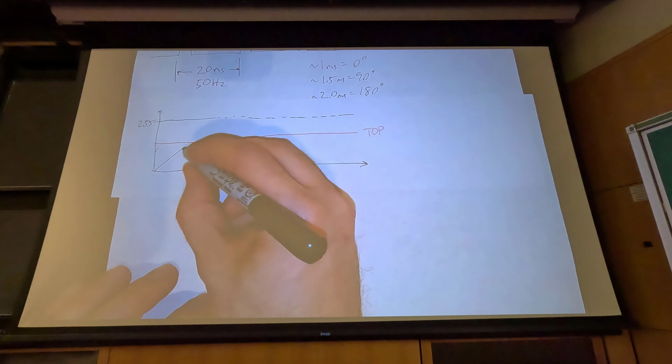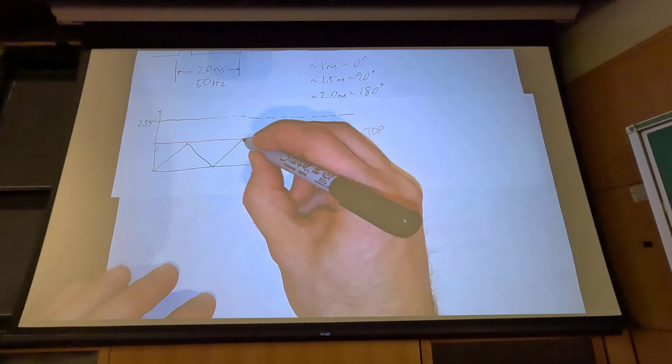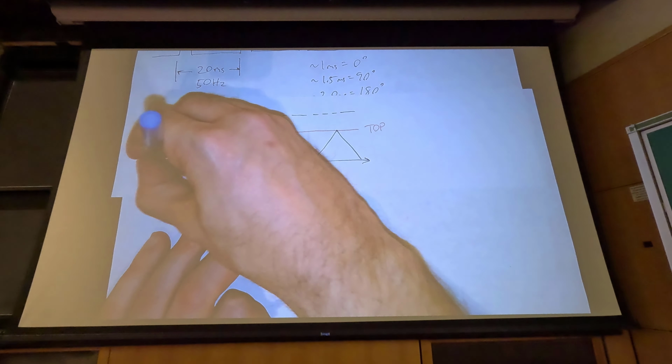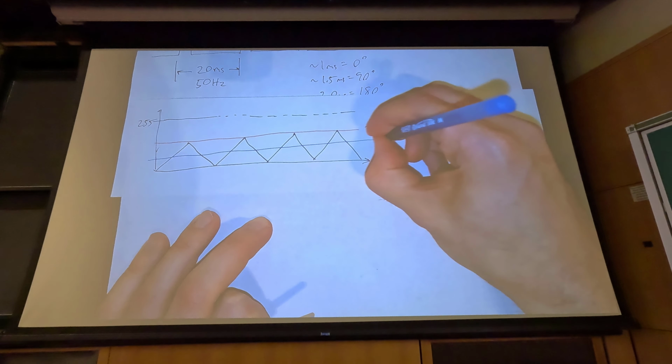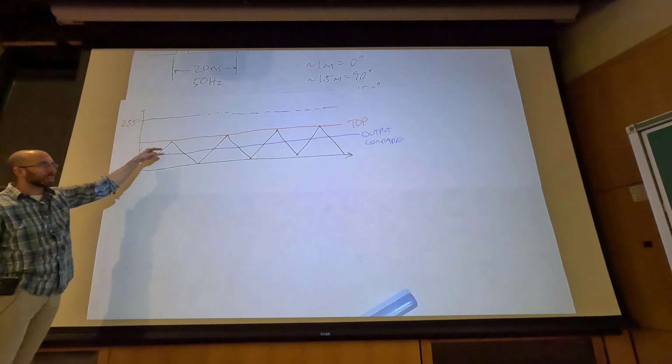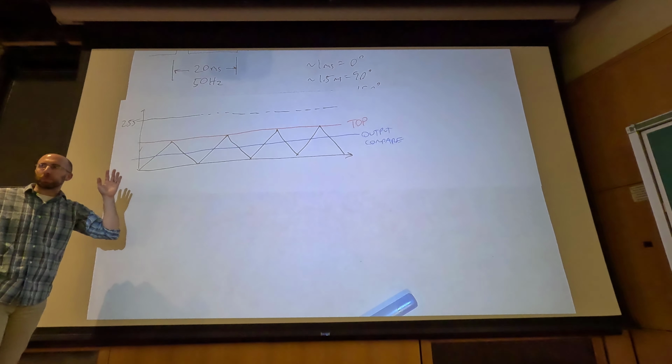Timer is going to do just what it did in the other PWM mode. It's going to count up and down, count back down once it hits that top value. And we are also going to select an output compare value. And changing that top and output compare value is going to allow us to control both the frequency and the duty cycle of the output PWM signal.